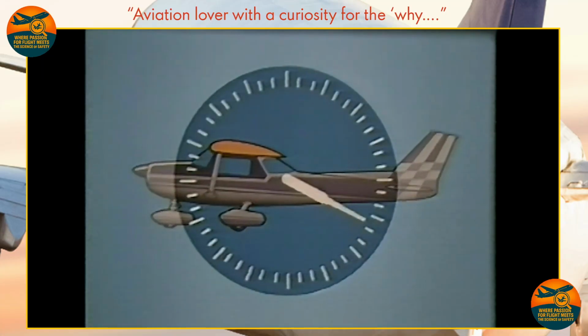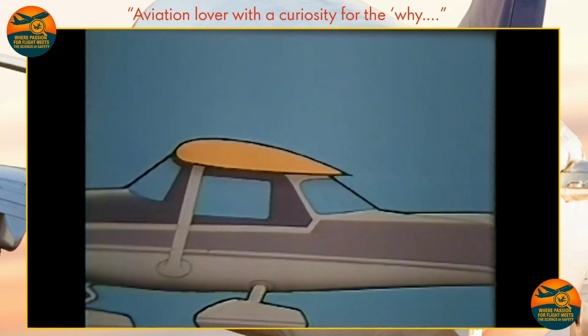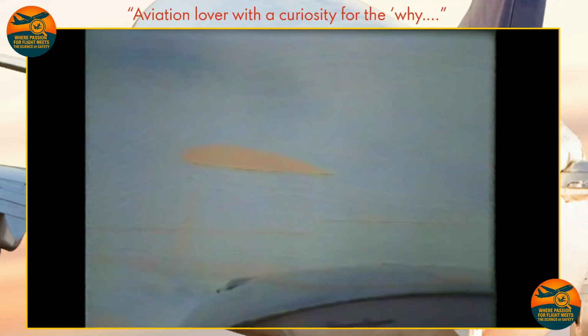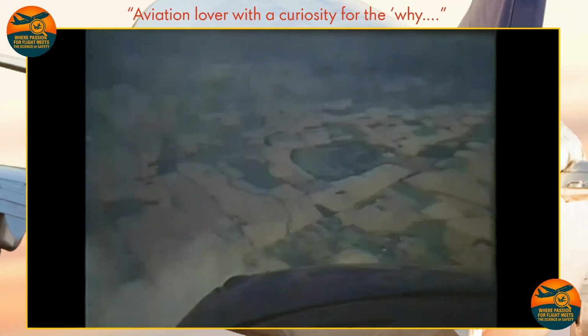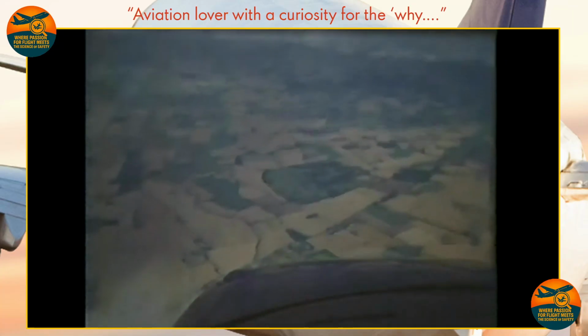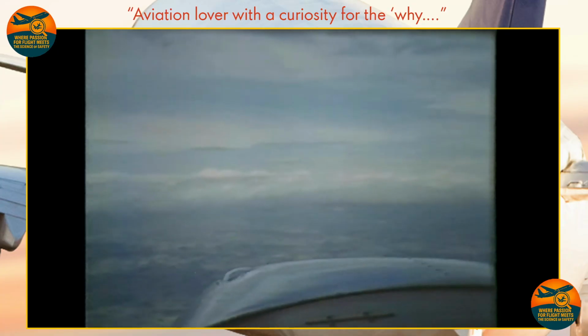But if the speed's allowed to decrease in level flight, lift will also decrease. Then if we try to keep the aeroplane level, it'll begin to sink. When this happens, the relative airflow gradually changes. If the critical angle of attack is reached, the aeroplane will stall and will drop momentarily out of control. The speed at which the aeroplane stalls will depend on its weight and will increase with altitude as the air becomes less dense.